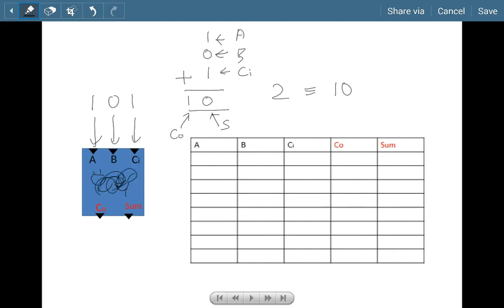That's not important. We will not discuss how to design the AND gates or the logic circuit in this tutorial, but suffice to say, you should understand what a FullAdder helps you do based on some designs of AND gates and OR gates. So 1 plus 0 plus 1, you should expect the result to be a 0 for the sum, and the carry out to be a 1.